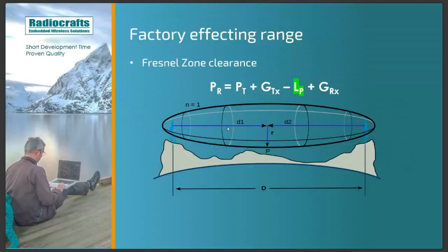So if you are standing on the ground looking at a transmitter 100 meters away, you do have line of sight because you can see between them, but in terms of perfect RF connection, you would have to put the antennas up on 100-meter tall towers. Then you will have a perfect connection, and that is the theoretical connection.